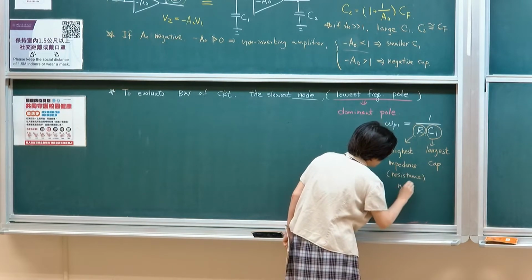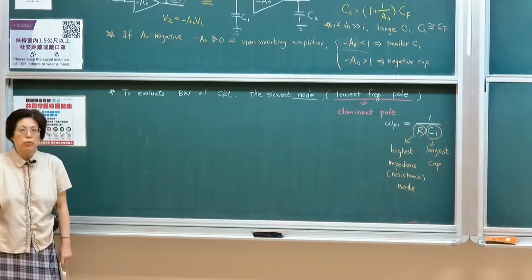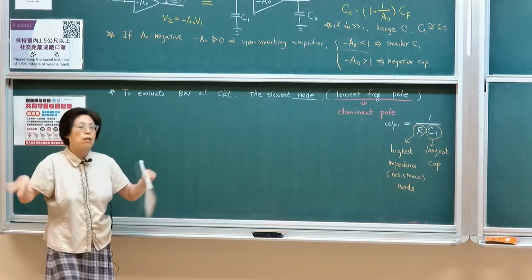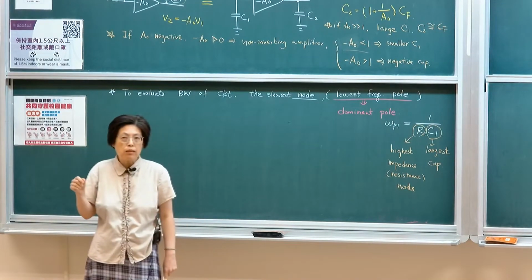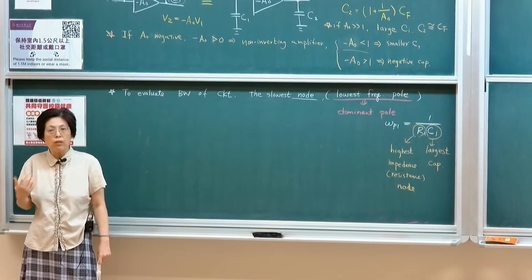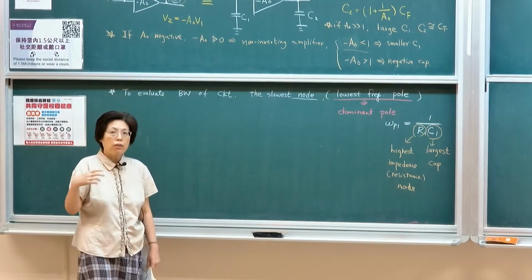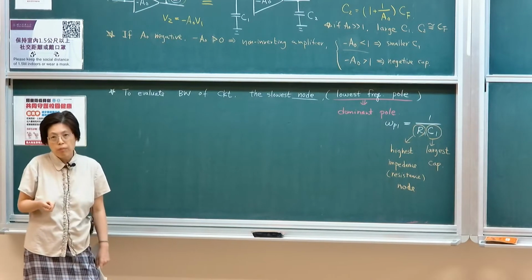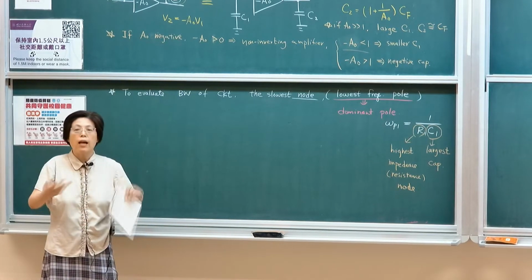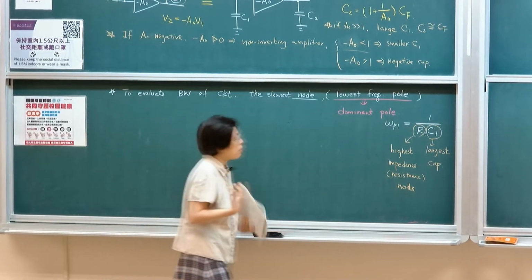or high resistance node. The way to think about this is that if I have, say, 10 nodes along the circuit, how do I find the slowest point? The slowest point will have the largest baggage, meaning it has large capacitance associated with that node. The other thing is that it has very little charging power, meaning it has low current to charge up the node. This simply means that it has high resistance, therefore the charging current will be limited by this resistance, okay?